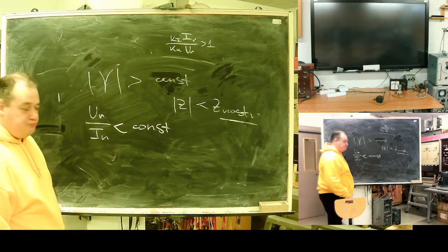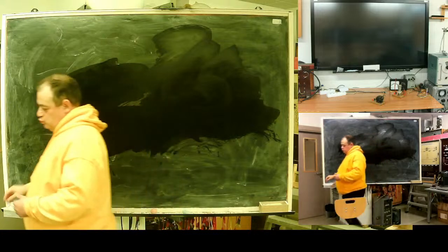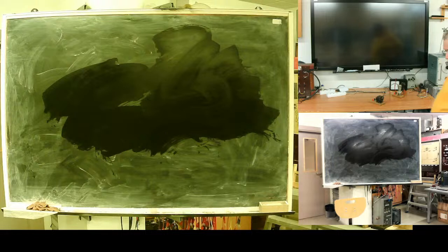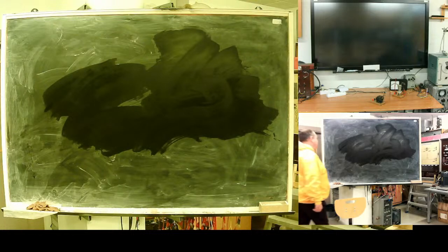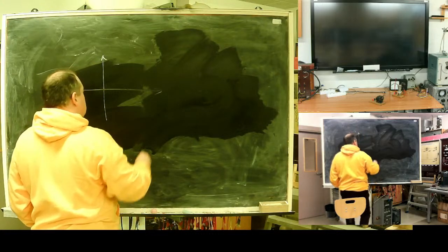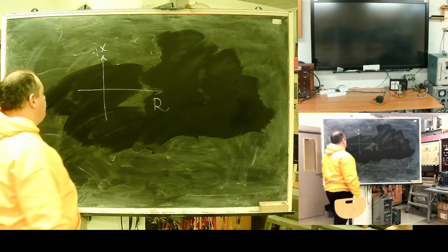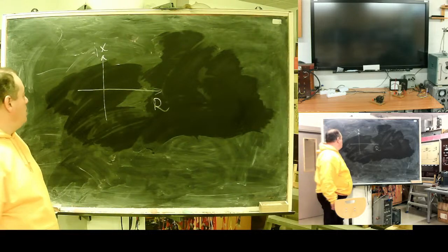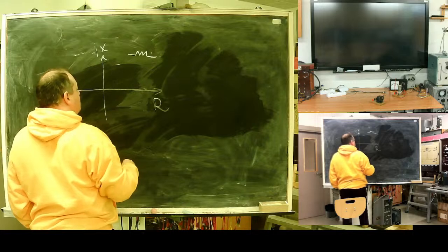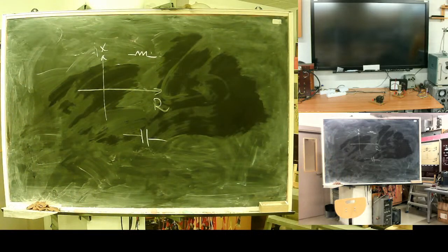Is it good or is it bad? We need a way to analyze, and for analysis a special tool can be incorporated. It's a complex resistance plane. The active resistance is considered real, inductive reactive positive, and capacitive reactive negative. This is our analyzing tool.